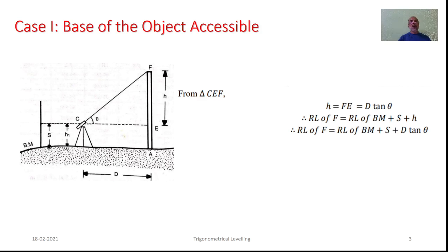As you know, we have to measure the vertical angle, and for that here we have to refer to the altitude level tube. So as we define the horizontal plane with respect to that, we can sight the station F and we can have this vertical angle theta measured with both face left as well as face right conditions. So the average of that angle can be expressed as this theta.